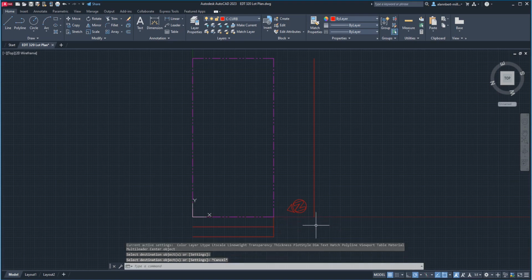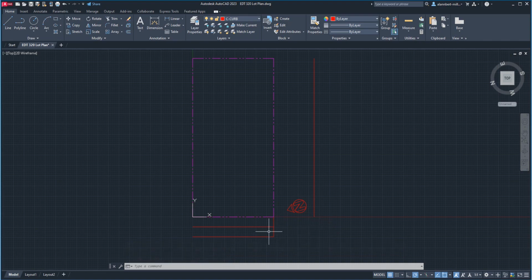Okay, so this is going to have another sidewalk like this. You can actually extend this line or copy that line, start from there, press enter, copy this line, extend from there, press enter, and then also do another line from here to here, press enter. We want to cut this off, so we're going to use the trim command, T-R-I-M, trim, and then simply select this and select that to cut them off. So this would be the alley, and this would be 34th Street.